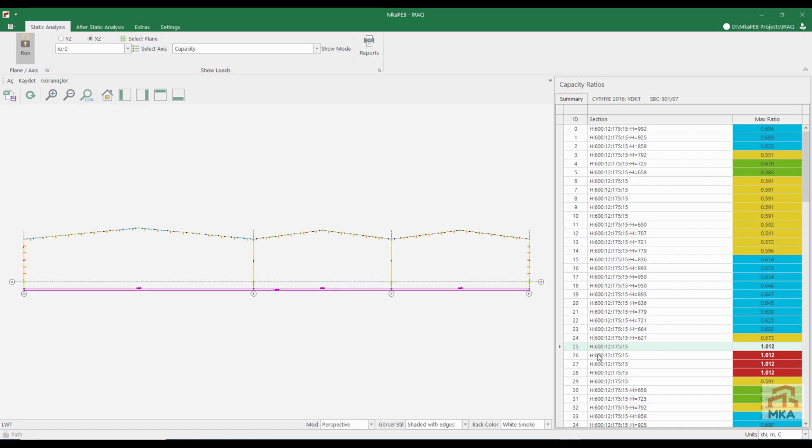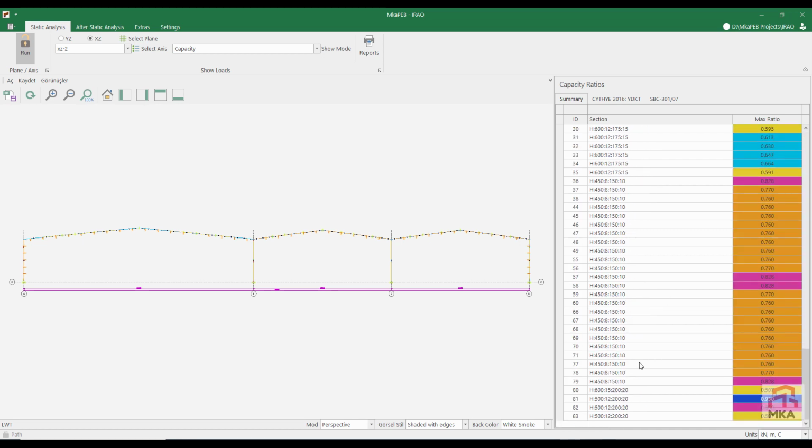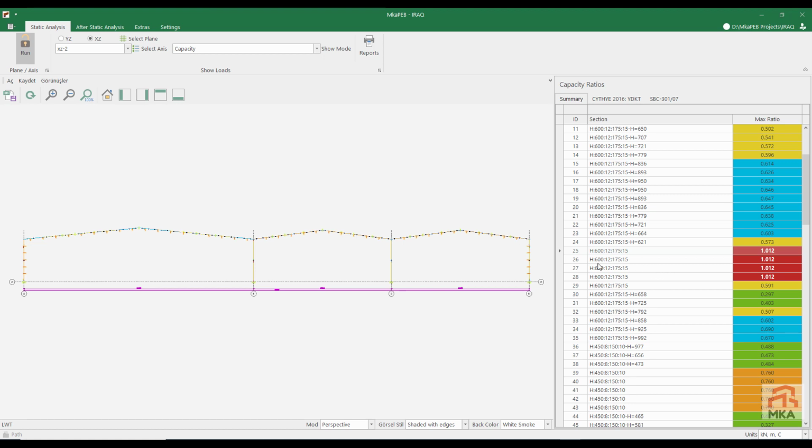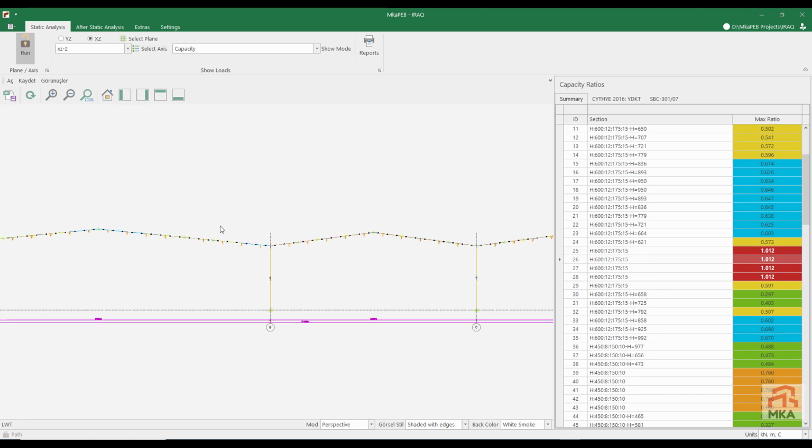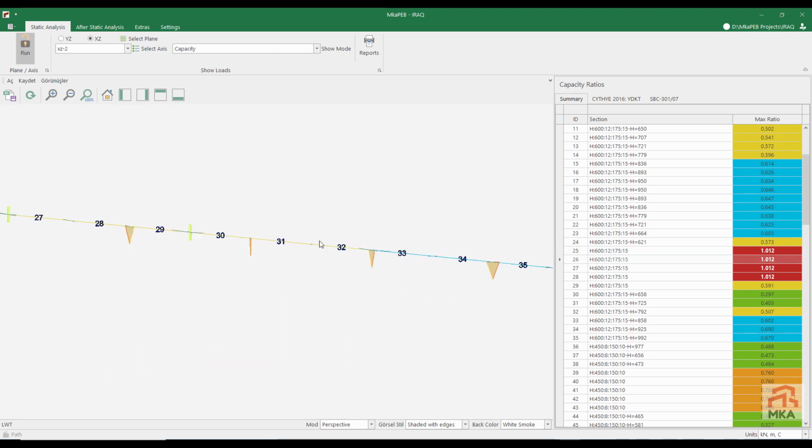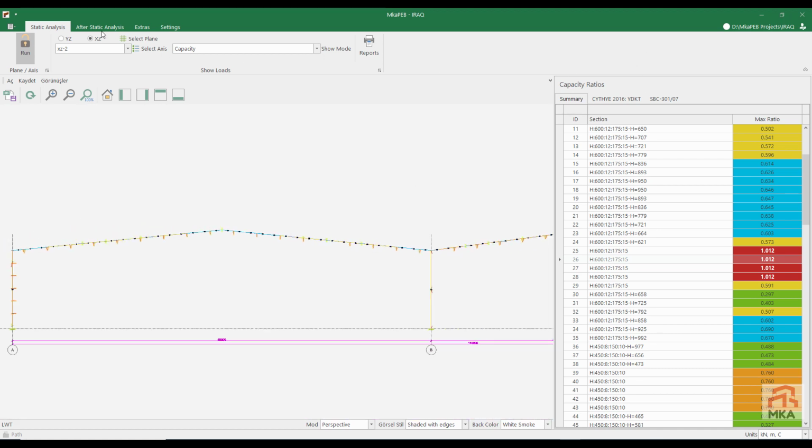It is green when viewed as such. What's not green? There is a lateral buckling problem on the 25, 26, 27 over there. We forgot to put one lateral support in between and the program realized it. The program warned us. We know that sections are not a problem. Let's not look at it again now, as I'll be repeating the analysis in a moment anyway.